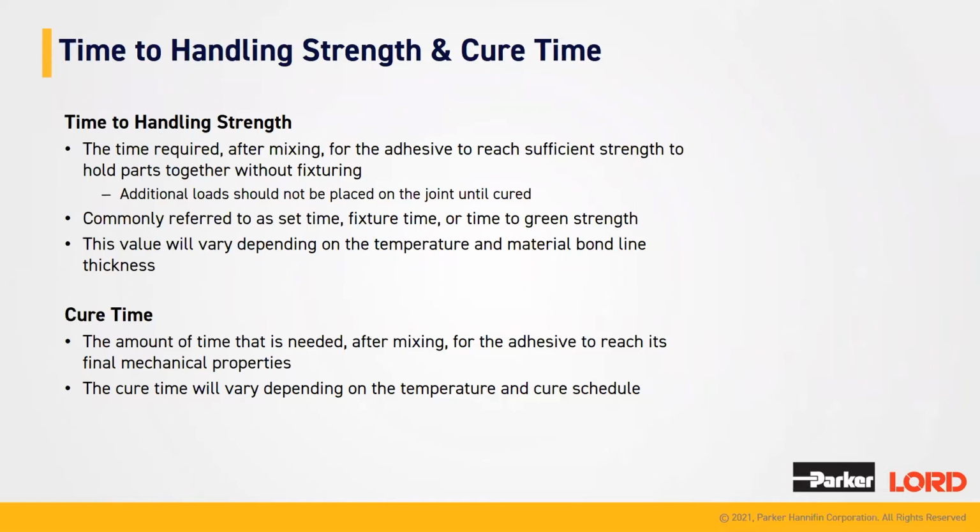So this time to handling strength is also commonly referred to as the set time, the fixture time, or time to green strength. And this value is dependent upon temperature as well as the bond line thickness, the amount of material that is used. Next, going on to the cure time.